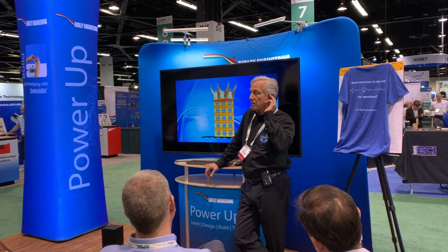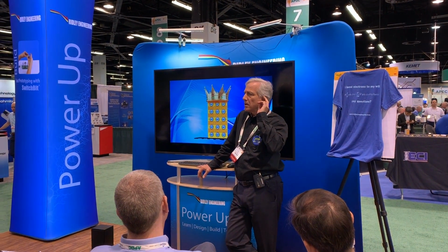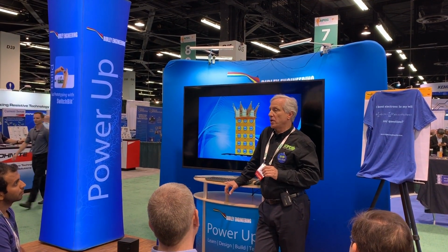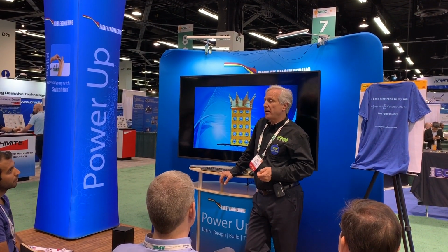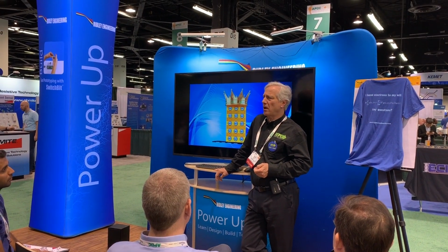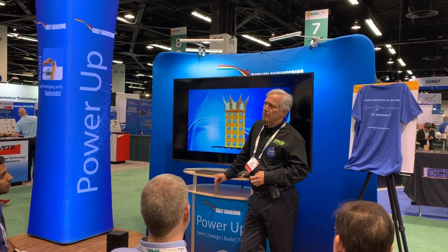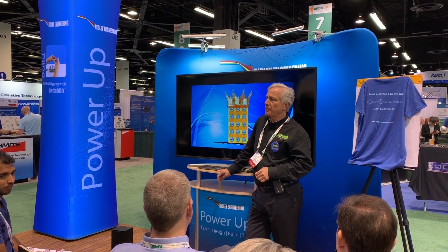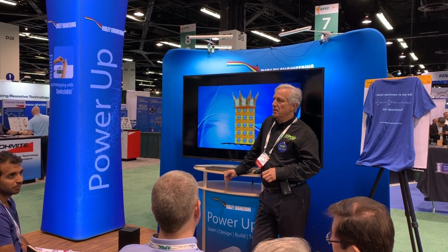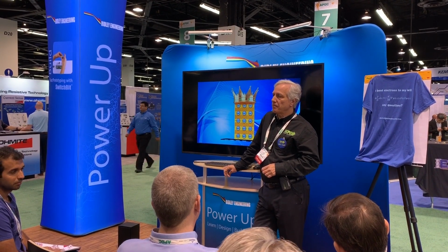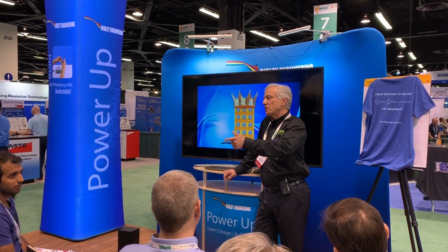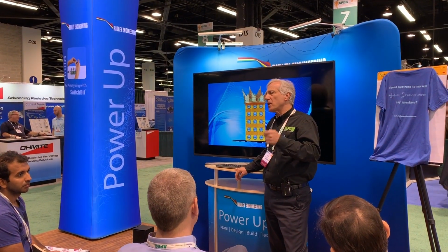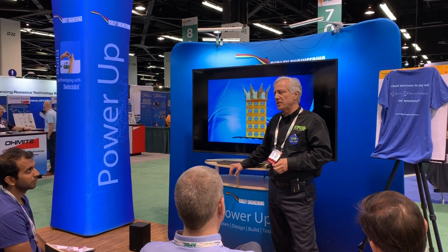Can I get 45 amps? On the half bridge, we don't have a 200 volt half bridge. But on our discretes, yeah, you can get better than that. The EPC2034 is like 30 amps, something like that. And when you look at DC current, sometimes that's just a specsmanship thing. But in our case, most of it's limited by electromigration.